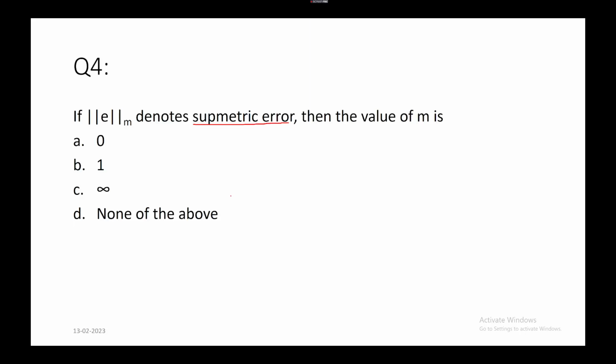Sources of error we have come across: the discretization of the element, numerical errors, computational errors. Correct. Those are all sources of error. So you have approximation error, then the computational error. Under computational error, you have two types: arithmetic error and quadrature error. And the third one is the domain error, which we saw just now, the computational domain error.